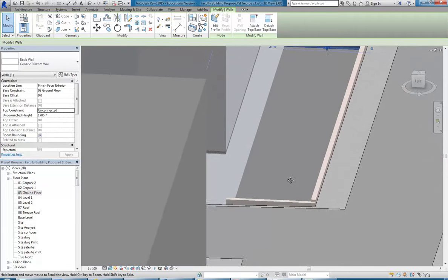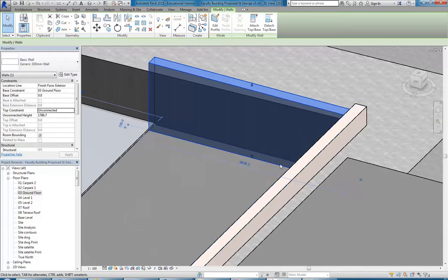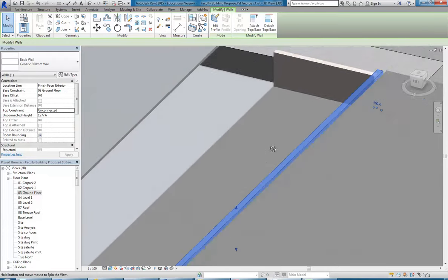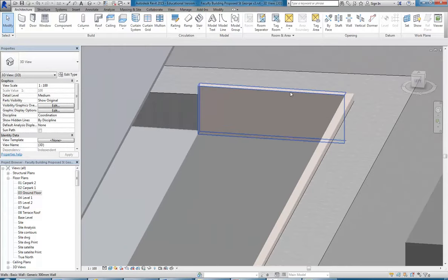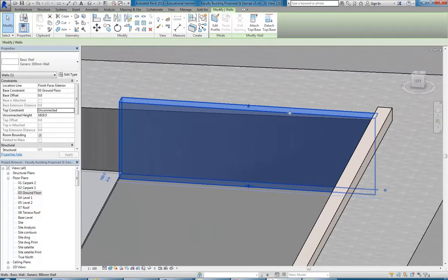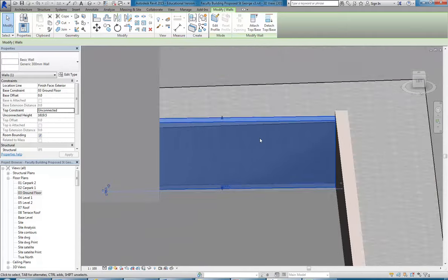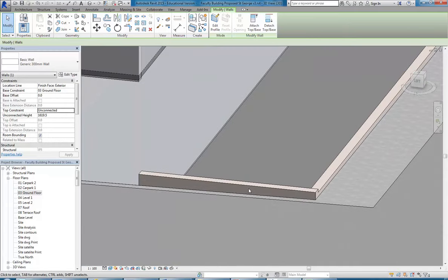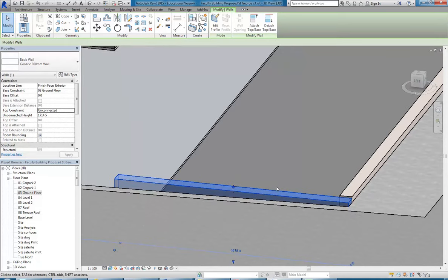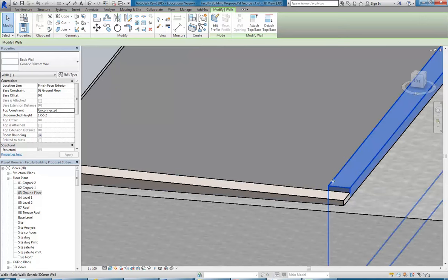Revit, and you'll see here that I can easily have this wall brought down so that it has maybe this wall at the end still higher than it, and I'm just going to drag the arrow there to bring that height down. And then this one can come down a bit further as well, so that's stepping down fairly naturally with the wall at the back maybe being higher than the one that's coming at a right angle to it. But then this one here, if I bring that down, notice how it's not stepping properly. This one at the end should be going all the way.